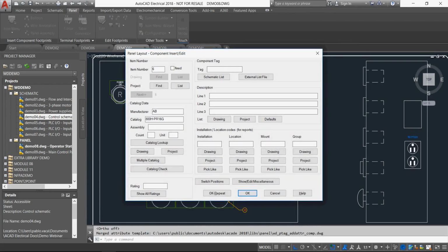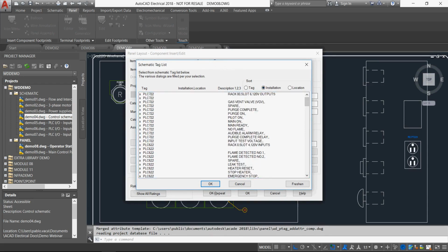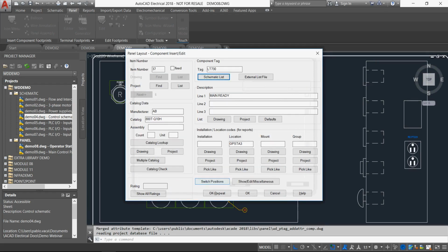Now it's going to ask you to link this particular footprint to one of our schematic components that we have already placed in our design. And here, once we select the component that we want to attach it to, everything gets automatically updated.